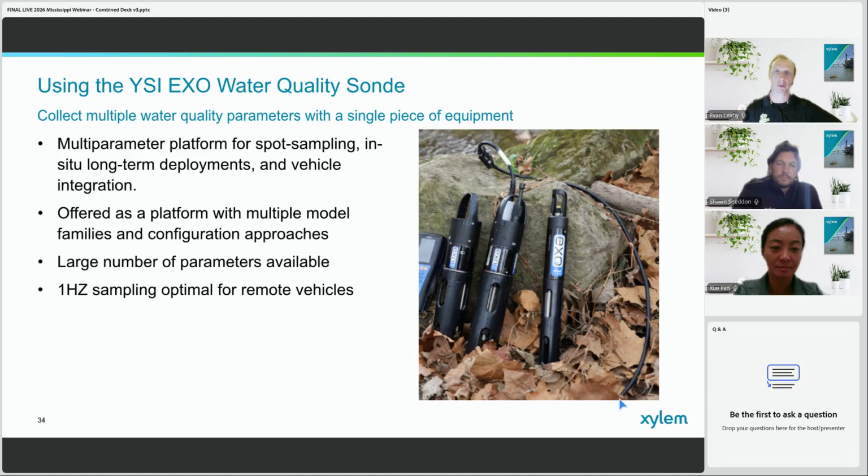If it loses comms for 10 seconds, it'll automatically turn around and come back to that launch location. So it's low battery or loss of comms, and it'll RTL, return to launch, and that launch location is set where you arm the vessel.